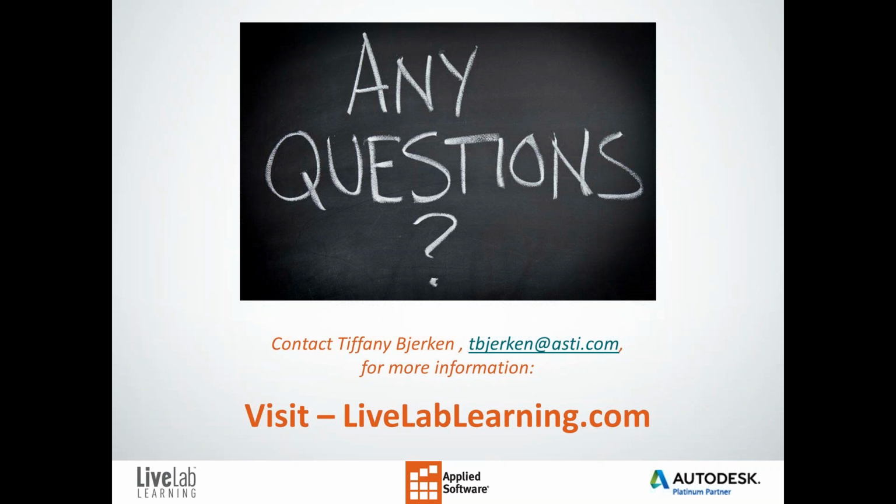Okay, we did have another one come in, and this is a three-part question, so I'll do the first one first so we don't get confused. When you refer to auto-registering for point clouds in ReCap, does this mean that sphere point references are auto-generated and aligned to make the point cloud? No, what it will do is recognize faces, or a series of points that are faces, so it'll try to recognize different groups of faces and then align them. It doesn't do anything with spheres.